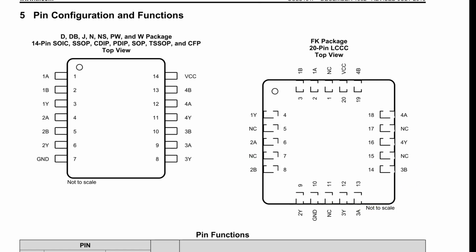You might think, oh, these pins are hidden on the bottom of the chip, so I've got to flip the chip over in order to look at the pins and see which is pin 1. This is top view, so don't fall for that one. And there's the pin 1 identifier, which will typically be a silk screened or a laser marked circle on top of the package. But not all packages will have that.